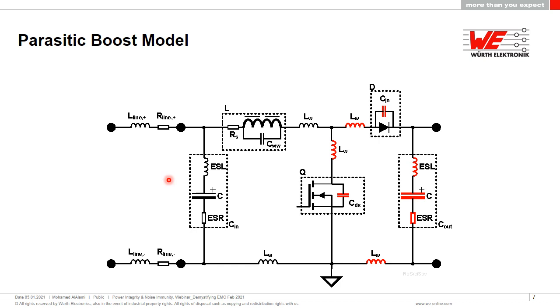So what are these parasitic issues that we can see? A simple capacitor, for example, we can start off with. A capacitor ideally is just a capacitor, but realistically you've got an equivalent series inductance and an equivalent series resistance. These parasitics could be the inductance and the resistance of the wiring, the cabling, and the actual tracking within the PCB itself.